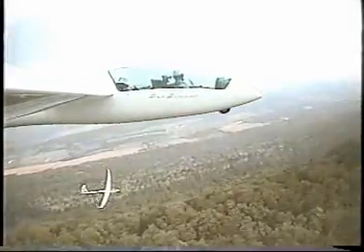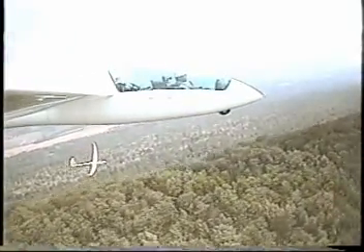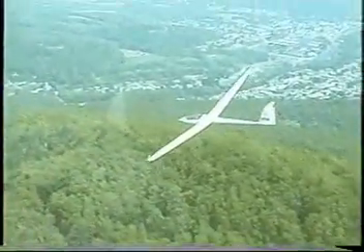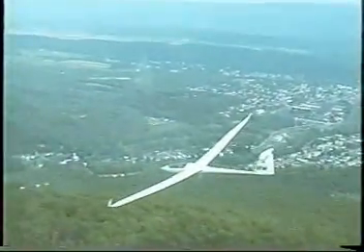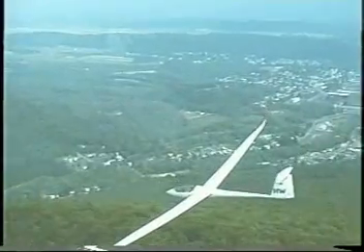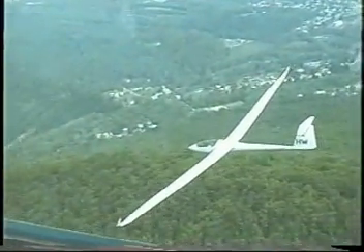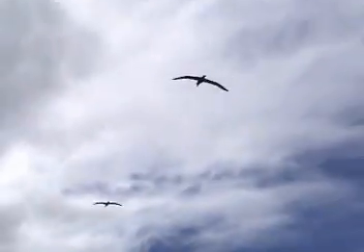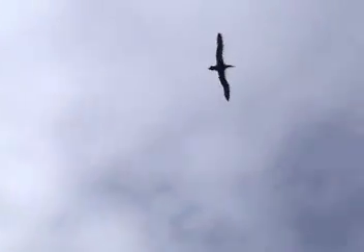The airflow over a glider wing is approximately two-dimensional as well, since the wing span is much larger than its chord. Such a wing is said to have a large aspect ratio. In this case, the wingtip and root are so far from a section at mid-span that they may as well be infinitely far away. A similar argument can be made for the wings of this waved albatross, more than 3 meters in span.